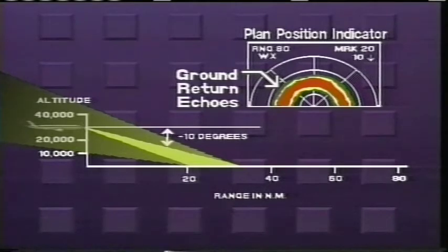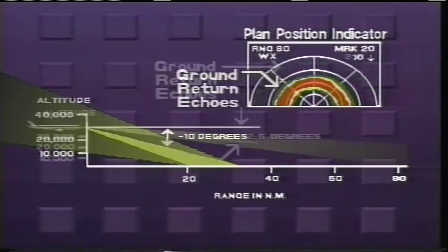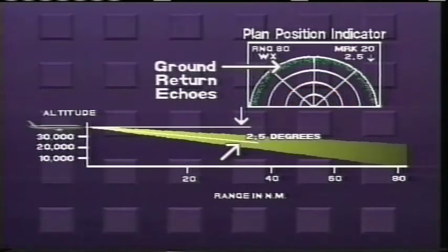At this point, you can think of the radar's beam as illuminating the Earth's surface in a manner similar to the way a searchlight, mounted on the front of the airplane and pointed at a similar angle, would illuminate the ground in front of it. Now, slowly increase the tilt angle to lift the beam. As the beam is lifted, you will be able to see the ground stripe reflection moving further out in range. Weather radars typically scan from one side to the other side in about 4 seconds, so be patient and make the tilt adjustment slowly. Continue to move the beam outward until only the outer edge of the display range contains ground returns, let's say about 5% of the display.